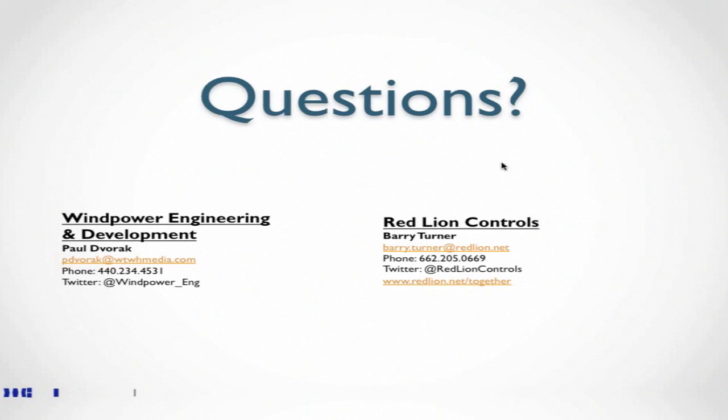Okay, and Peter asks again, what is the advantage of having a defined ringmaster over a solution where the lowest MAC address becomes the ringmaster automatically? Well, we're able to say where the ring is. Like RSTP, for example, which is kind of the IT data world's redundancy protocol. It selects the root bridge, which is equivalent to the ringmaster. It's selected by the lowest MAC address.